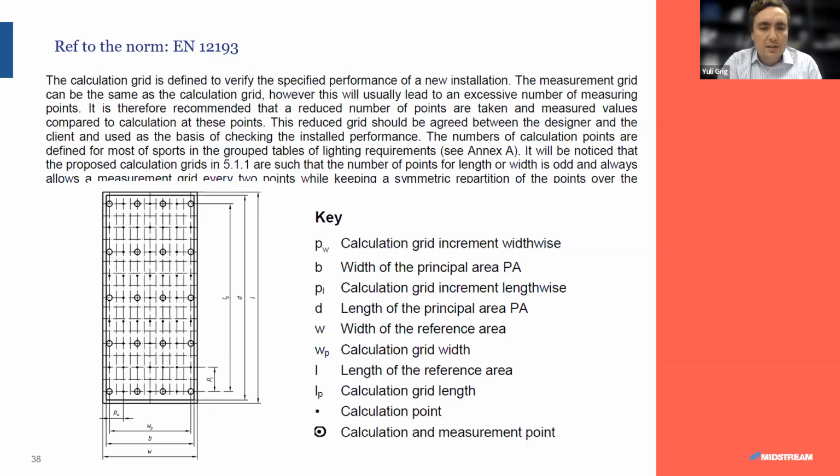Another question here, I think we'll just have to go for the quick wins. Faizul asks, is the shadow of aircraft needed to be considered for apron lighting design? And the answer is no. Lighting design is considering no aircraft shadowing. However, what you can do is place the 3D models of the aircraft inside the simulation software to demonstrate where there will be a shadowing issue and how it can be tackled.